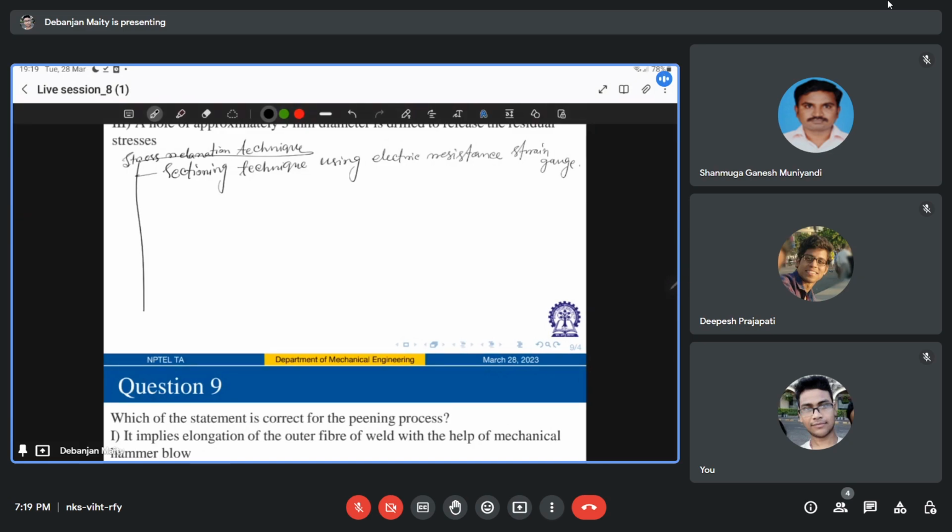What happens there? In this technique, gauges measure strain or displacement by the change in electrical resistance in a coil of wire or foil that is mounted on the surface of, let's say, your test workpiece, right? A very small piece of material containing this strain gauge, in the weld or adjacent to the weld, should be carefully removed by machining.